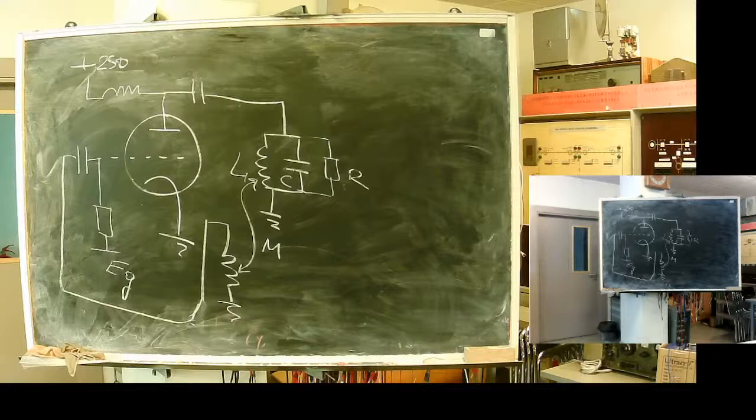This one is made in the so-called universal system. The sections are like discs, and inside the wire goes not just turning, but always like a wave to increase. What to increase? It's to increase quality. It means decrease interwinding capacitance. Works. Okay.